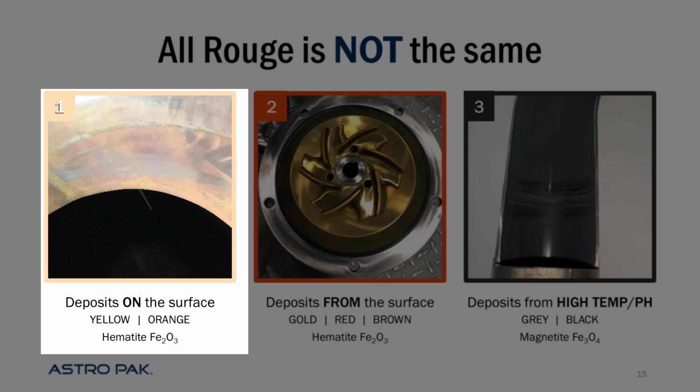The corrosion source, where the passive layer broke down, is elsewhere in the system. It is not where I'm inspecting right now. That iron oxide has been generated at a different surface, and it has sloughed off through the process flow rate onto the surface I'm inspecting. The iron oxide compound right there is hematite, ferric oxide, iron 3+.